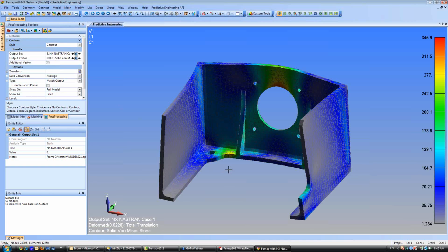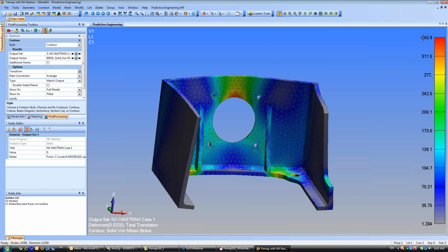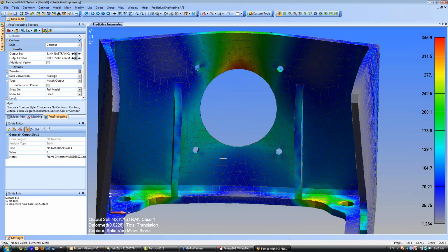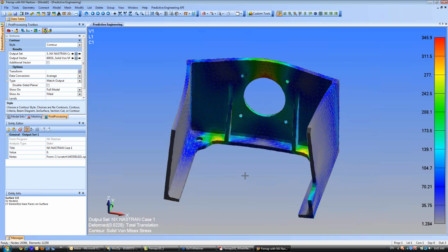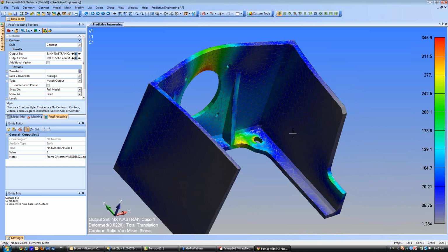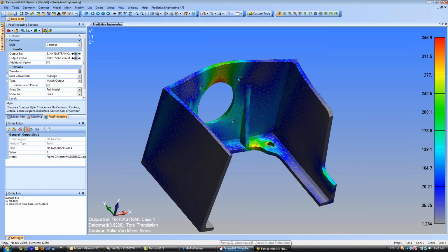Contour. Voila. So there. We started out with about 470 in stress units. We went to 400, now to 345 by moving the design around. And very quick, very fast. This is my favorite form of optimization. You can't beat the human mind. You can't really beat just looking at stuff and figuring out the load path and doing some quick little studies. There will always be jobs for good engineers to move things around. So that takes care of that example.